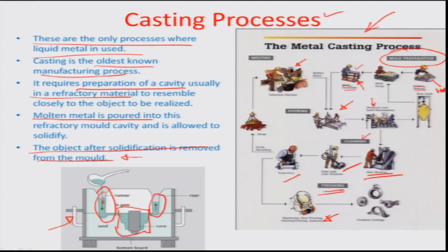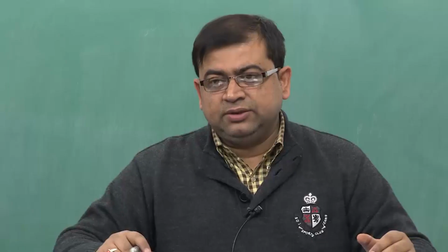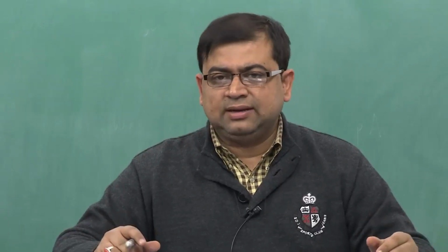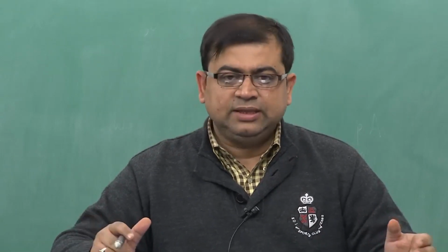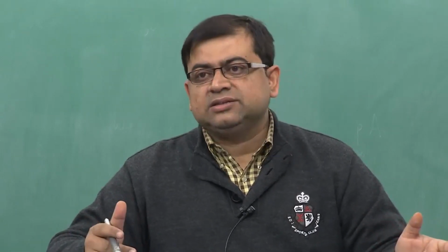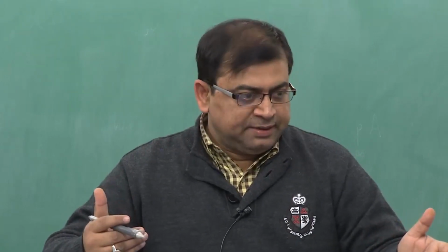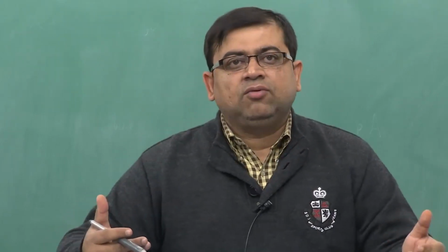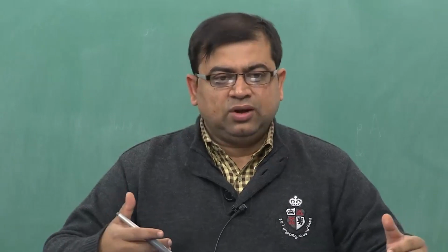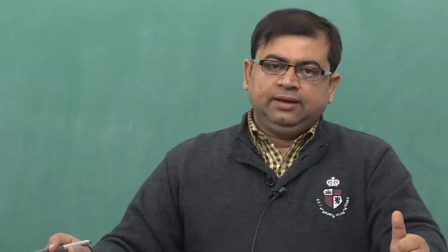So this is just an overview of how a casting is done, but there are many intricacies and many modalities in terms of process modeling, where you can actually figure out what is going to be the length of the runner versus the riser, what is going to be the time it takes for the liquid metal to reach, and during that time what is the impact of solidification on the material, or for example when the material gets to fill the cavity, after that what is the impact of the solidification on the overall grain structure. All these aspects need to be revealed in great detail when we do the section on the casting area, or process modeling for the casting.